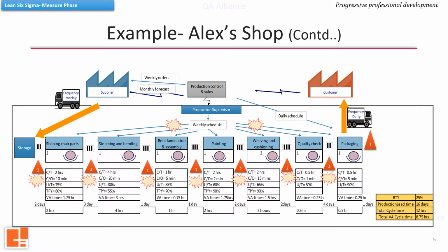As discussed earlier, these maps should not be drawn sitting in the office. Unless we go on the shop floor and capture information as is, a VSM is of no value. A big wall can be utilized to draw the as-is process. In this hypothetical and simple example, we started with identifying the departments involved and then captured information like their interaction, information flow, inventory, cycle time, etc. We also observed the real value-adding time and noted that down at each step. This helps in identifying the gaps and assessing the magnitude of improvement that is possible.